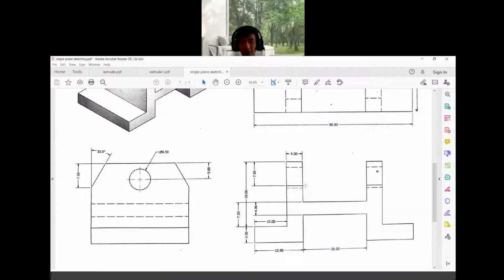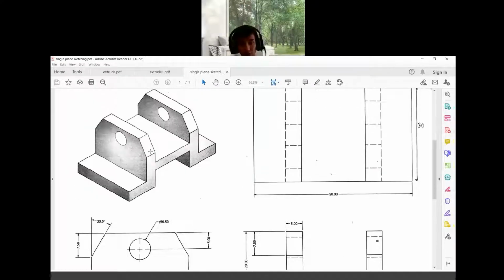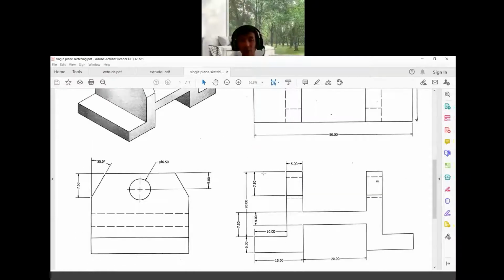This is a chamfer. As I mentioned, in Inventor, if it involves chamfer, holes, fillet, shell, and so on, we ignore it in our sketching. Okay, we ignore it. Later you will see how we are going to add these features. Added features are relatively easy. So we are going to do that towards the end of these progressions.